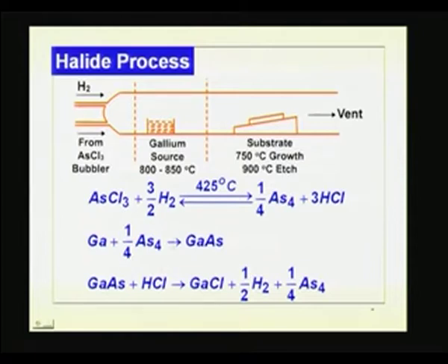This is a graphite substrate, you keep it at an angle so as to get uniform deposition all through. To get uniform deposition, you keep it in the tilted position, so that even if the vapors get depleted, you get higher velocity, so that diffusion takes place more on this side. The result is you get a uniform layer from this end to that end.